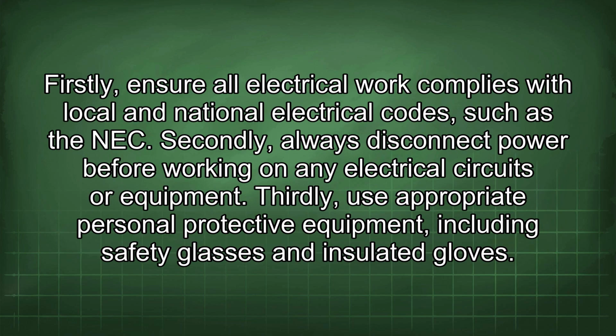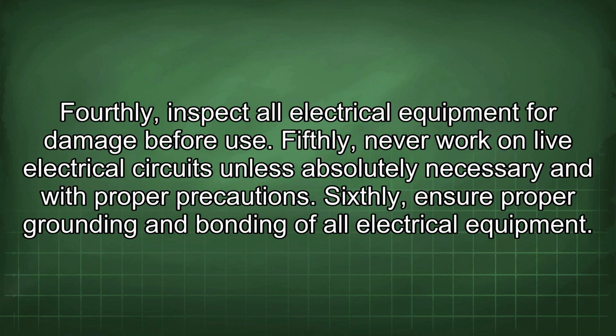Firstly, ensure all electrical work complies with local and national electrical codes, such as the NEC. Secondly, always disconnect power before working on any electrical circuits or equipment. Thirdly, use appropriate personal protective equipment, including safety glasses and insulated gloves. Fourthly, inspect all electrical equipment for damage before use.